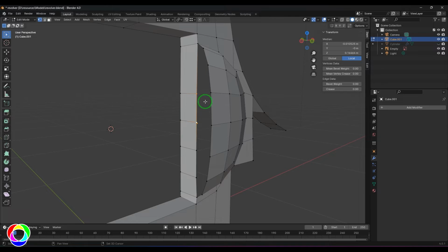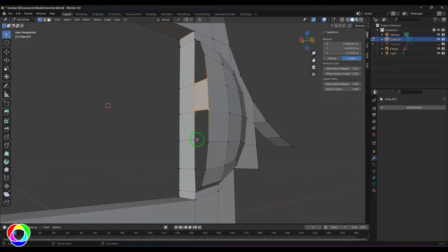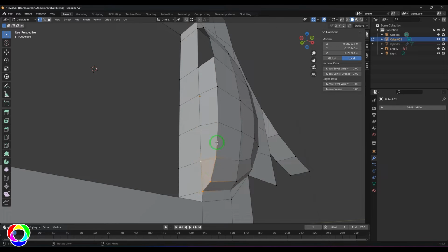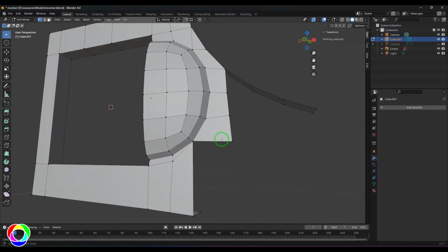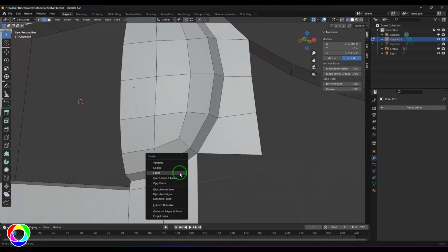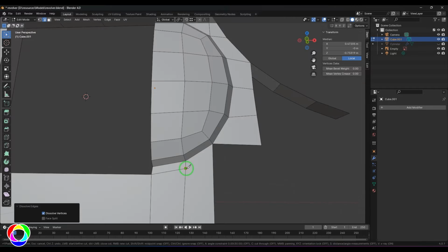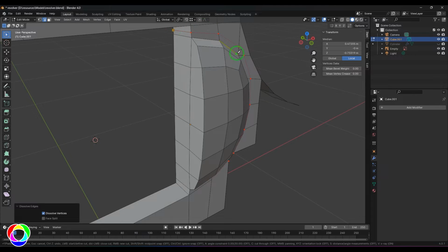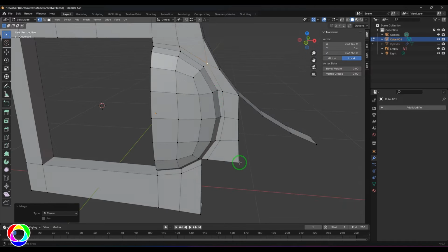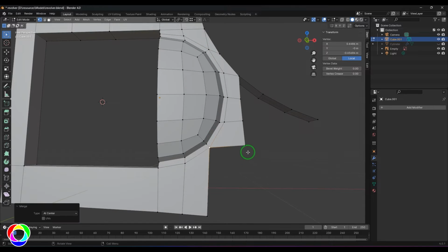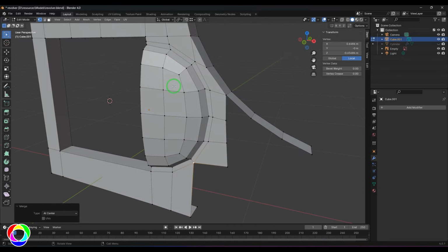So I'm going to select those 4 vertex points, press F to fill, and then start filling those points one by one. Okay, I've filled those points here, and the lines have come correctly. So I'm going to add a line here close to it. Once that is done, I got a loop here. So I'm going to select those 2 vertex points and merge to center. So that I got that nice line. Now when I apply mesh smooth, I get the creases correctly.